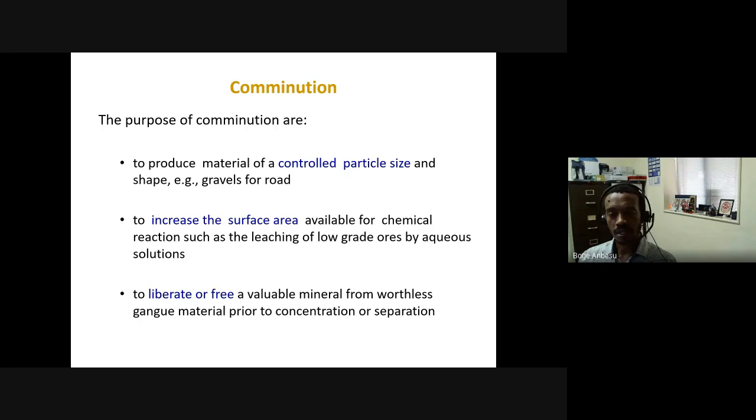So comminution is done typically to improve liberation of particles, create more free particles. Once we produce more free particles made from one mineral, then we can talk about separation or beneficiation after that. So to generalize, in mineral processing, comminution is conducted both to generate new surface area and to liberate the valuable particles or the valuable minerals so that they can be separated from the gangue.